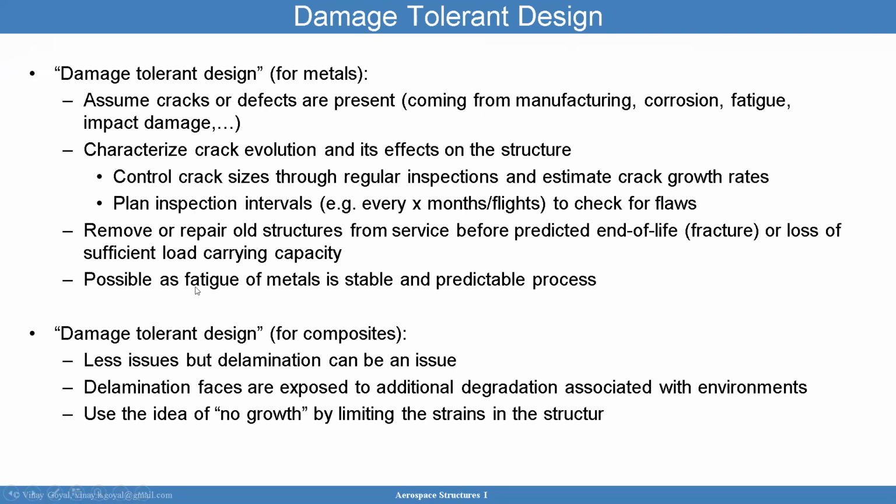There could be possible that the fatigue of the metals are stable and that things are okay. But you don't know that until you inspect every so often. Damage tolerant design for composites is less of an issue than metals. Well, impact damage can be an issue, but fatigue is not as big of a concern with composites typically. But delaminations can be an issue, and so you can do a lot of testing to gain confidence that you don't have a fatigue concern.